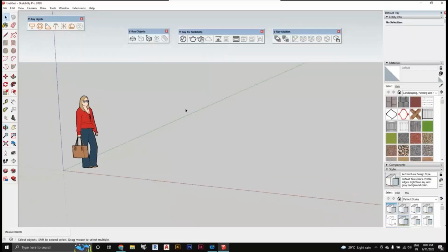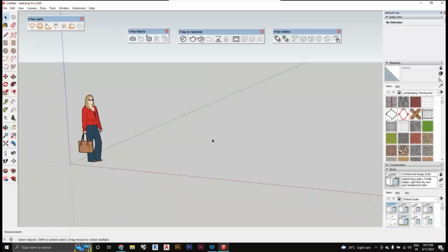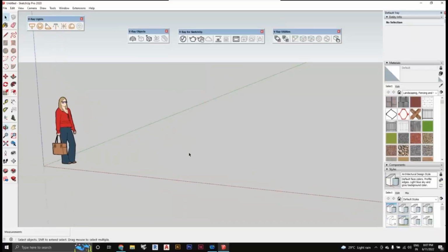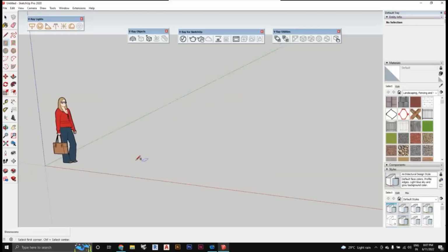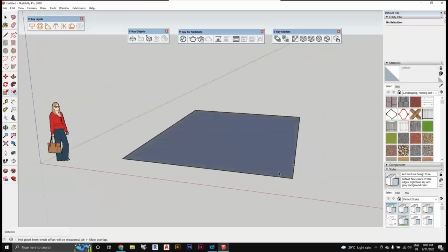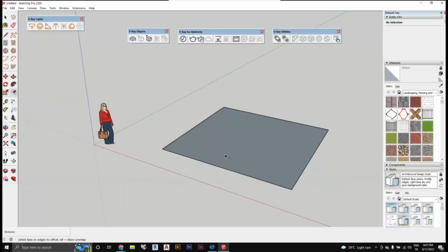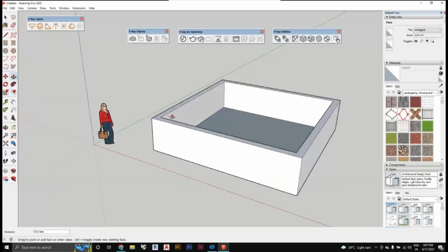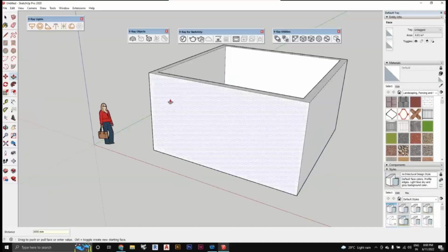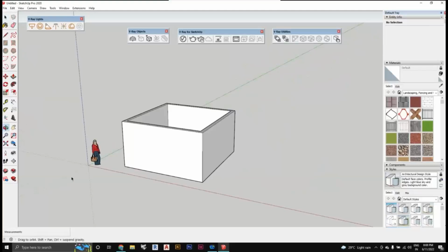The first one here is known as the mesh clipper. Mesh clipper is used when you want to render a perspective section, or a section. For example, I am having a box. I'm just offsetting it a little. I'll make it in a dimension so that it is possible: 5000 comma 5000. I'm entering it, then offsetting it like 230 mm and push-pulling it around 3000 mm. So you get a room space. I just made a room.